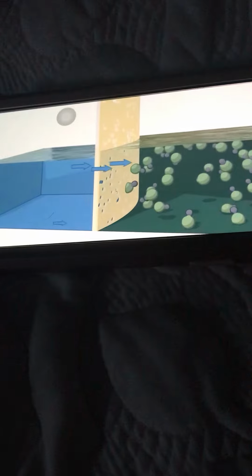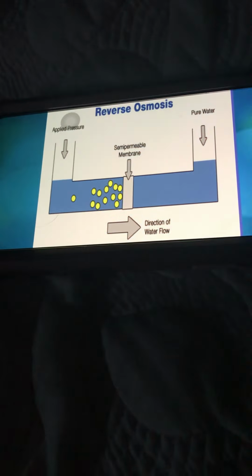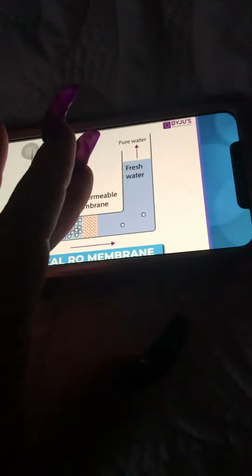Because the RO membrane has very small pores, the feed water needs to be treated before it can flow. Water can be pretreated chemically to prevent biological growth and lime scale formation and physically to remove all suspended matter. The high-pressure feed water flows through the individual membrane elements. The helical RO membrane elements are constructed.